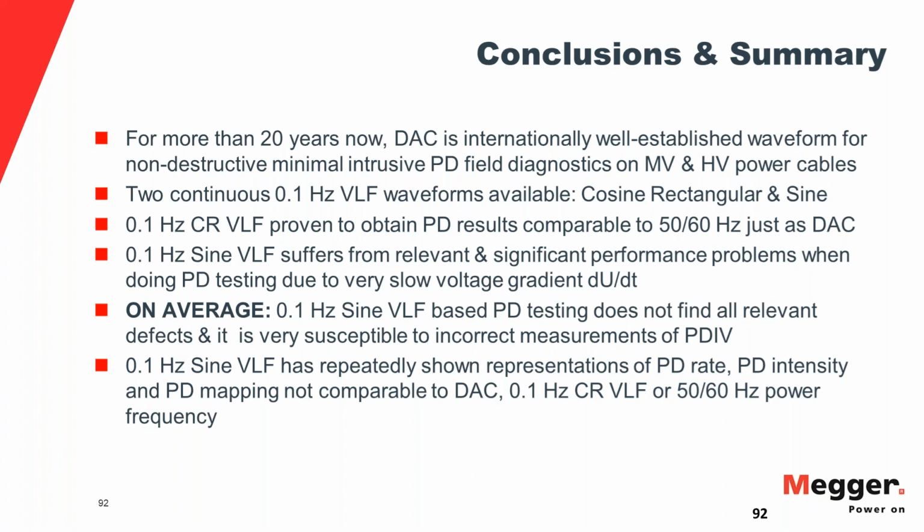Well, the latest, hottest thing in the industry is moving away from just VLF testing, going to monitored withstand testing, which means you do a fully compliant VLF test because you have to do this. It's your withstand test for the commissioning. But you record a diagnostics indicator, and that is for new cable installations, preferably the PD.